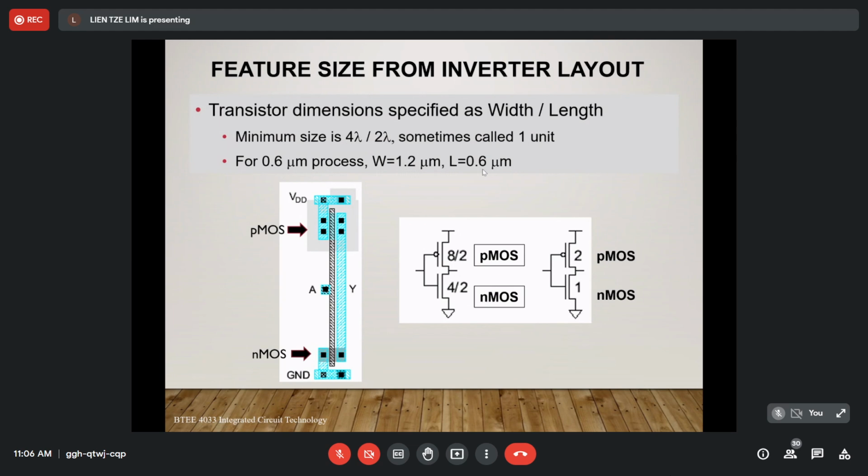If we refer to this figure, this is the schematic diagram, and this is the layout design of the CMOS inverter. These all are CMOS inverters. This figure shows the width over length of both transistors, PMOS and NMOS. As you see, the feature size for PMOS is 8 over 2, and NMOS is 4 over 2.